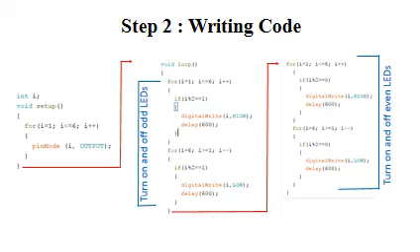If the value of I is odd, which is checked in the if part of the code, then the LED will turn on by getting high voltage, and there is a delay of 600 milliseconds after each turning on. So the loop will turn first, third and fifth LEDs on sequentially.